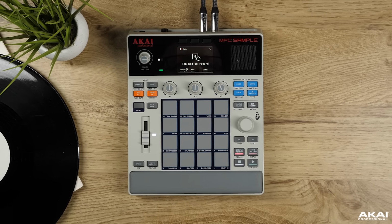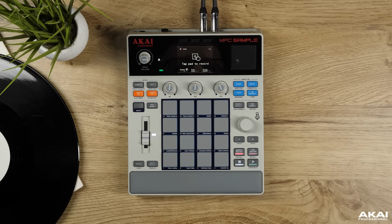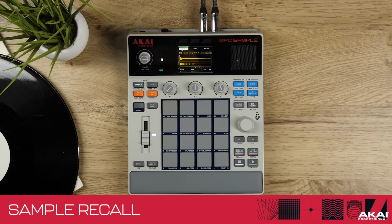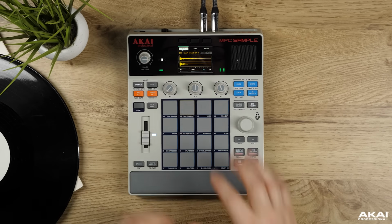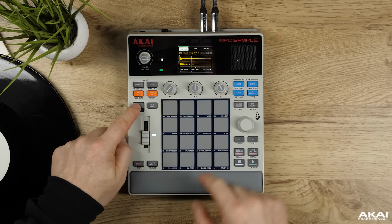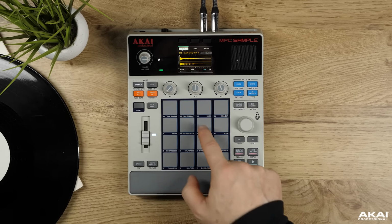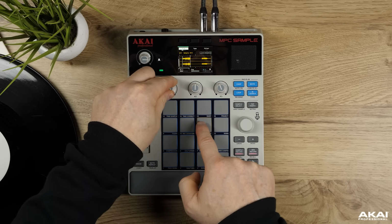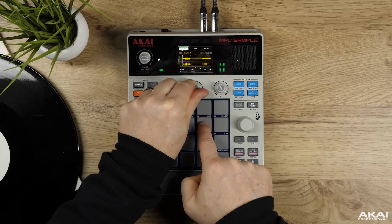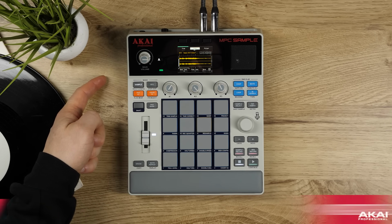To sample, simply hit sample record and now select your input source from the microphone, rear inputs to USB and resampling. We also have sample recall, which is continually recording in the background. So if I play a melody, I can recall this as a sample, hit Shift, sample recall, and it now puts it to a pad. There's what I played. You can now edit this, chop the sample up, add effects, and add it over your beat. You also have a micro SD card slot, which allows you to load and save samples and projects.